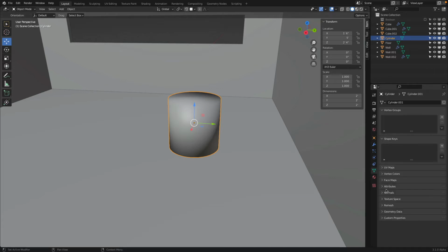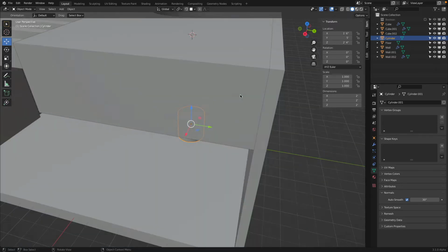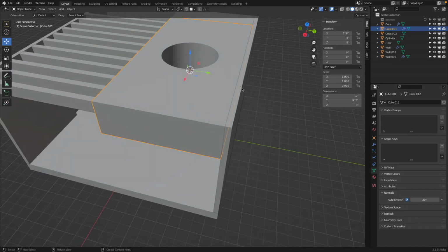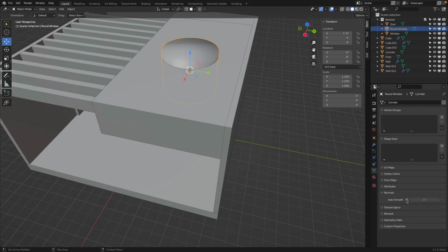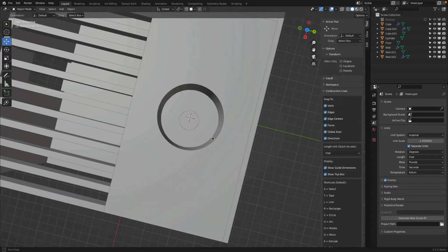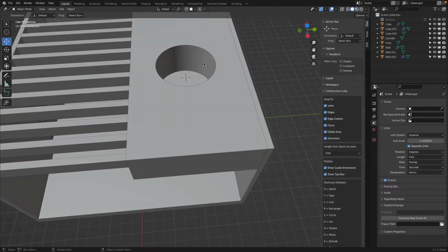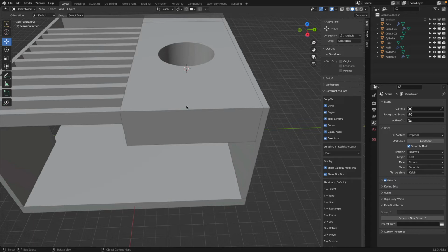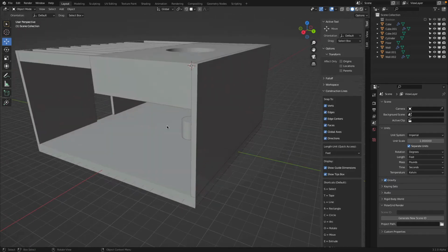We can go to this property here and normals and auto smooth. Basically what this means, break sharp edges. Now this is a sharp edge and this is not, so make this look round and make this not round. And we do exactly the same here. There we are. Oh, this is still faceted. Well, we have to do the same to this object. Okay, very good. You see, same steps. Now we have nice rounded shading in the inside and flat shading on sharp edges on the outside.